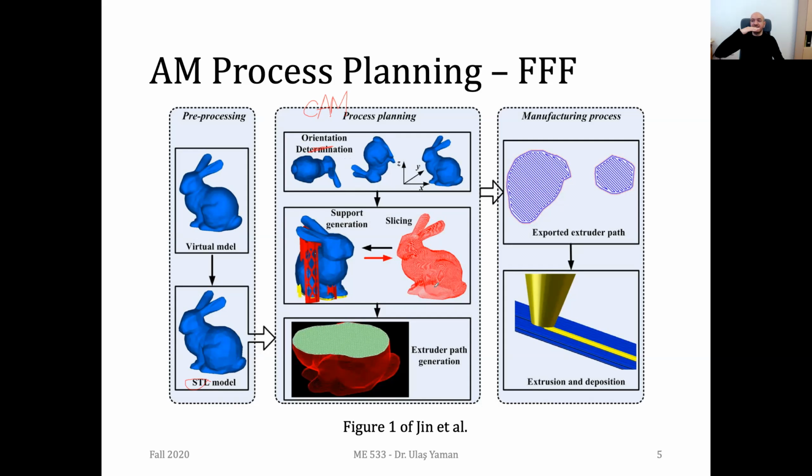slicing. And in slicing, as you have done in the third mini project and you are doing in the fourth, we are taking the slices at various Z heights, and the thickness of each slice is equal, it is constant. And then another thing the CAM software does is generate these infill patterns. You see we have completely filled the interior. This is a kind of zigzag pattern.